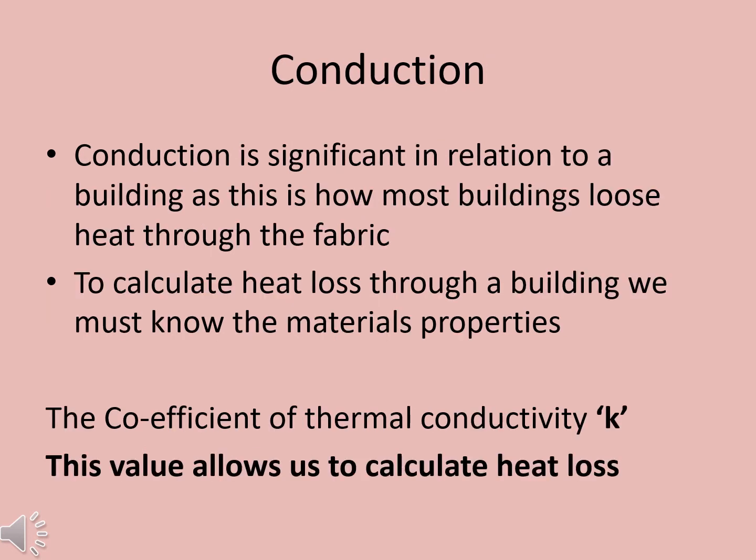Conduction. Even though there are three forms of heat transfer for a building to lose heat, the most significant one is conduction, as the majority of the heat is lost through the conduction of heat through the building's structure and fabric. In order to calculate the heat loss of a building, we first need to know how conductive the materials are and how much heat loss will occur. The conductivity of each material is known as the coefficient of thermal conductivity. It is known as a K-value.